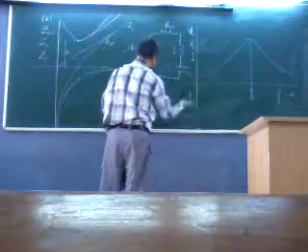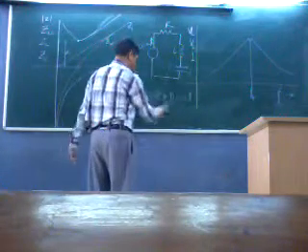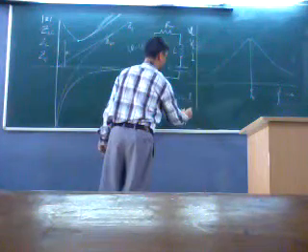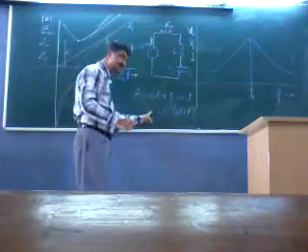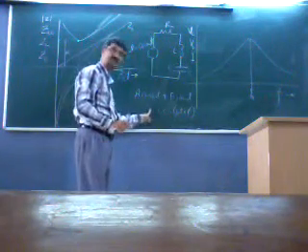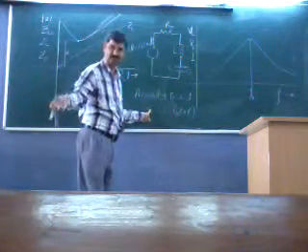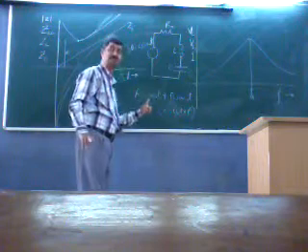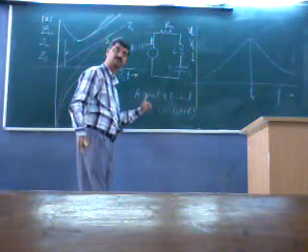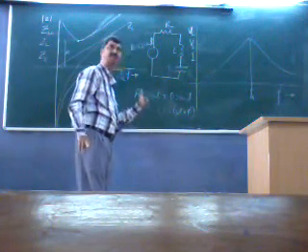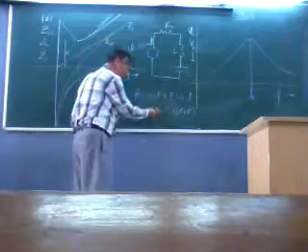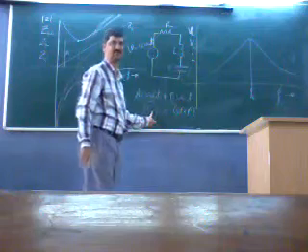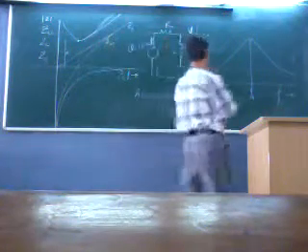Then when you get A and B, you can combine it into C cos of omega t plus phi. This C is the peak of the inductor voltage. Similarly, you will get some other peak for the capacitor voltage. This itself is a function of frequency, so you can differentiate with respect to frequency, d by d omega of this set equal to 0, to get its maxima.